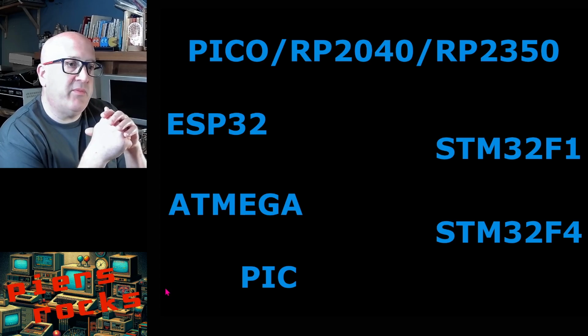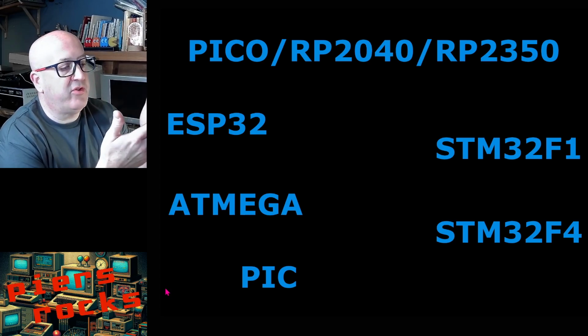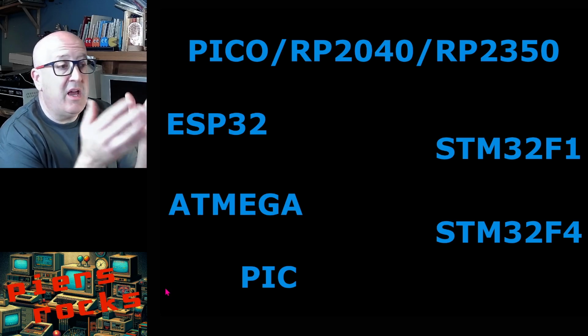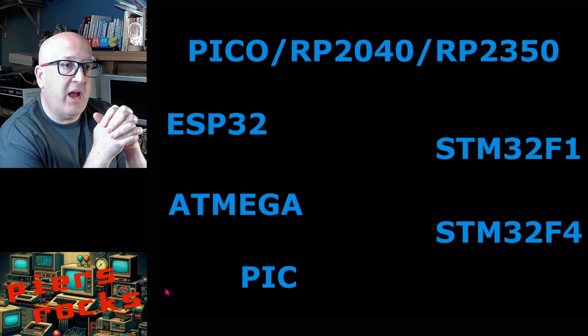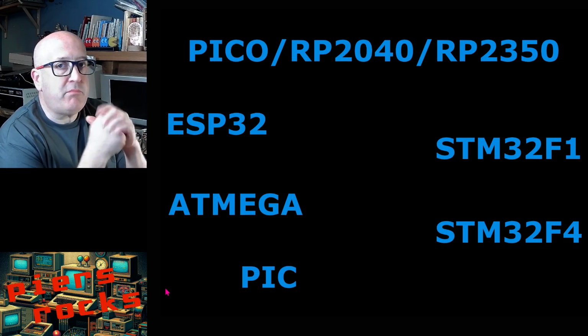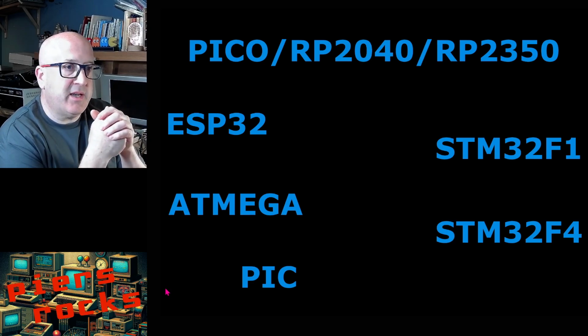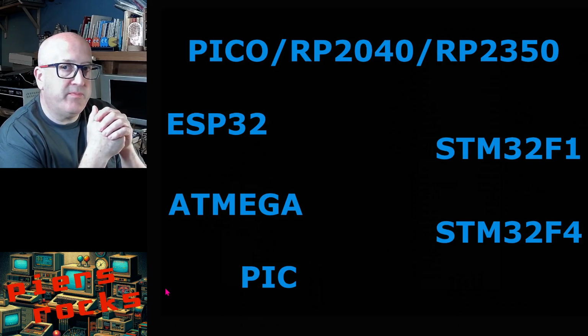So I settled on the STM32F4, and this comes in processors with maximum clock speeds all the way from 84 up to 180. It has really good instruction prefetching and caching for this application, which is quite simple. I found no wait states being introduced from flash whatsoever, and its 5-volt tolerant GPIO support is really good, really optimal for this application. So let's take a look at the schematics next and look at that optimal GPIO location.